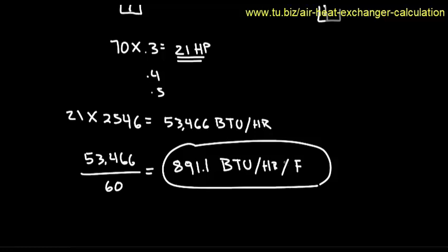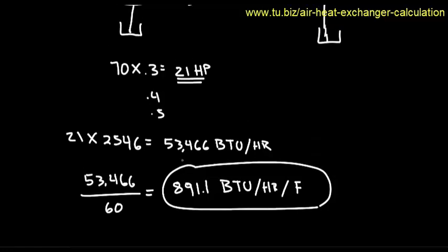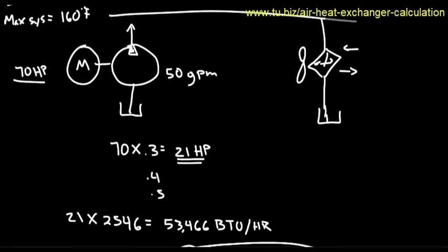I need to find a unit that can do at least this heat removal and that can handle 50 GPM. Or I would say, in this case, I'll say 50, but keep in mind that in the return line, if you have cylinders that are too big, you may have a higher flow than what the pump is putting out. So you may need more than 50.